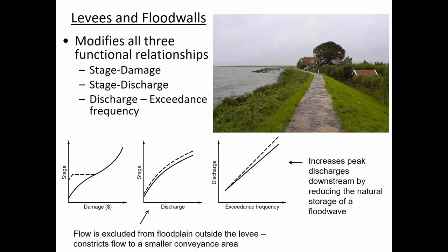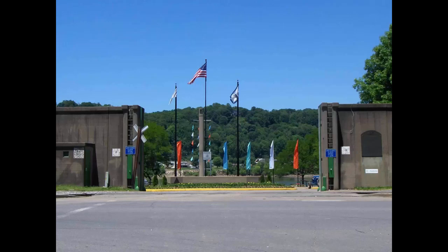And they probably, your point is you want to make the channel as wide as possible. Like you wouldn't build the floodway here, but the wider you can make the channel, the better. So they want to maximize the capacity, but the wider you make the levee, the less land you have for development. And so I think what they're trying to do, like in the Netherlands, for example, is balance how much land they want to reclaim versus how much flow carrying capacity they need in the levee.